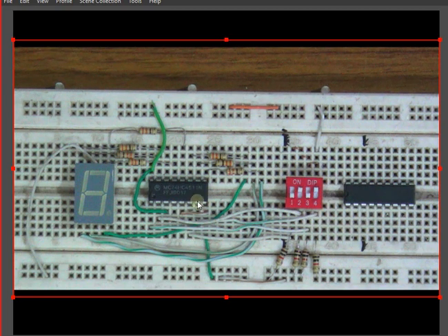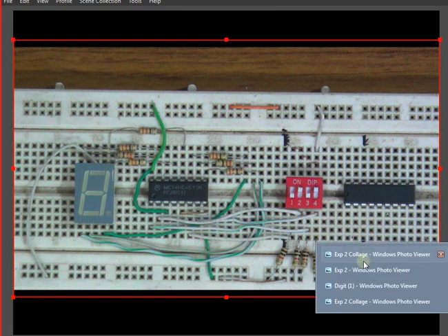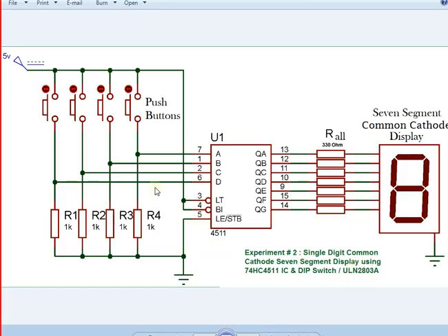So by having this 5 volts and ground, you are actually running this IC, you are giving a 5 volt signal to this IC, and when you are going to give dip switches. Now one thing only over here, if you see the circuit diagram back over there, if I don't connect these 1 kilo ohm resistances, these are going to be open, which means A, B, C, D are going to be not getting 0 volts.